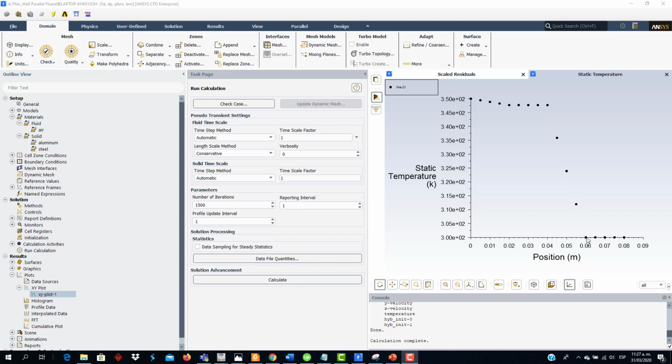sudden, sharp reduction in the temperature profile, and this is because this is the air layer where the air is located, and here is the rest of the profile where the upper solid is located, which is also aluminum. Then we can see here how the thermal resistance of the materials is affecting our temperature profile.